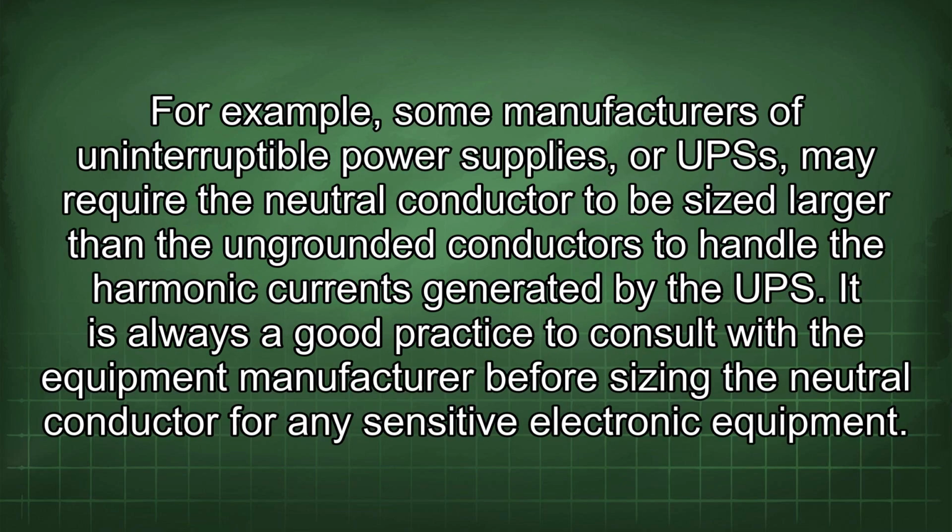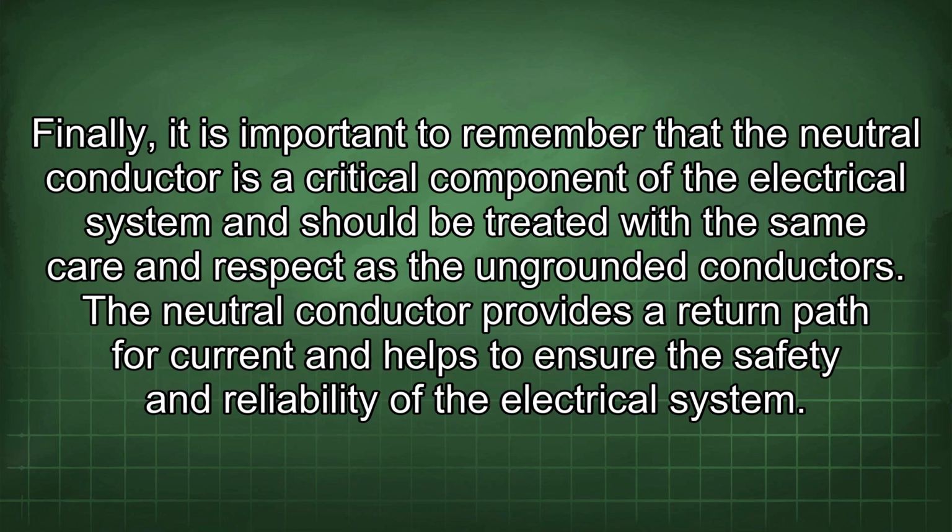For example, some manufacturers of uninterruptible power supplies, or UPSs, may require the neutral conductor to be sized larger than ungrounded conductors to handle the harmonic currents generated by the UPS. It is always a good practice to consult with the equipment manufacturer before sizing the neutral conductor for any sensitive electronic equipment. Finally, it is important to remember that the neutral conductor is a critical component of the electrical system